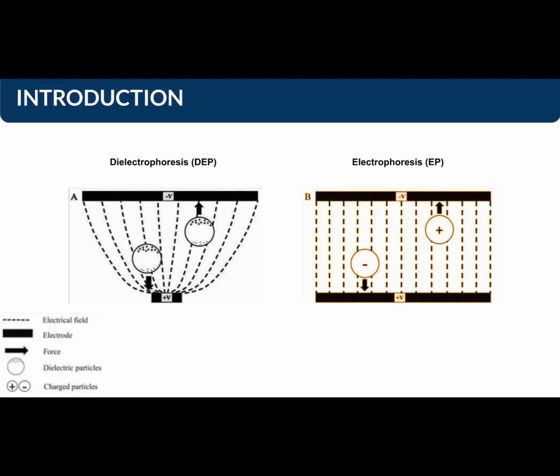Insulator-based dielectrophoresis is a usual technique, and it is achieved by using electrodes to induce an electric field on a medium on which particles will travel, and insulating obstacles that cause this field to become non-uniform. The non-uniformity is required for the polarization effect which drives electrokinetic forces. This novel approach allowed for the use of pure DC electric fields, and for the first time the competing forces of electrophoresis and electroosmosis were analyzed in the presence of dielectrophoresis.